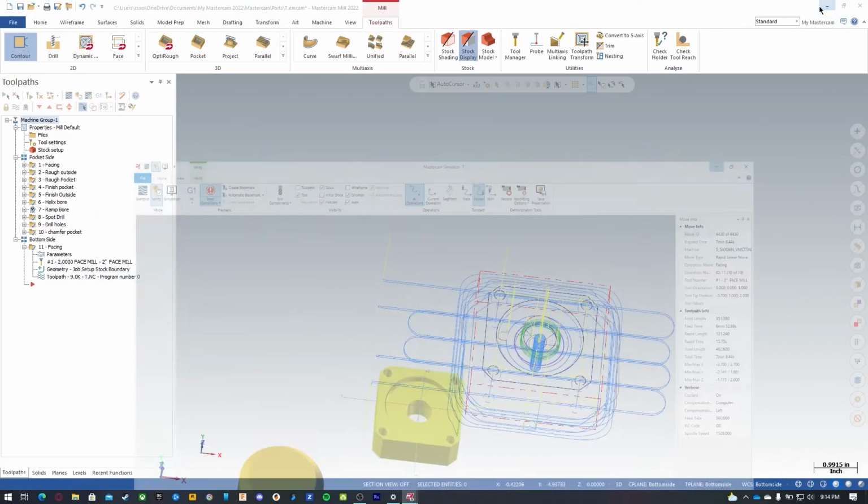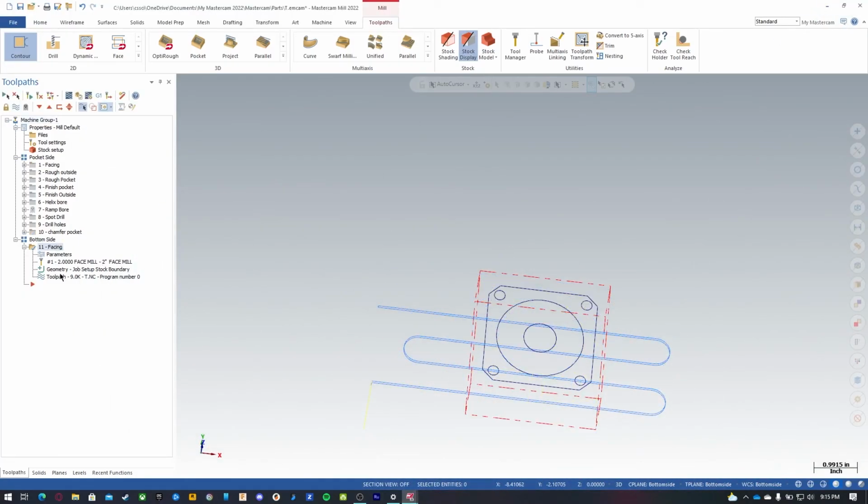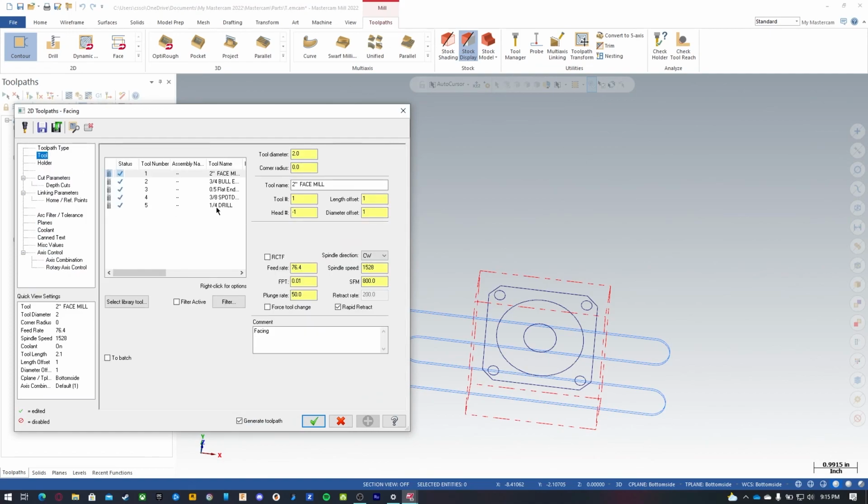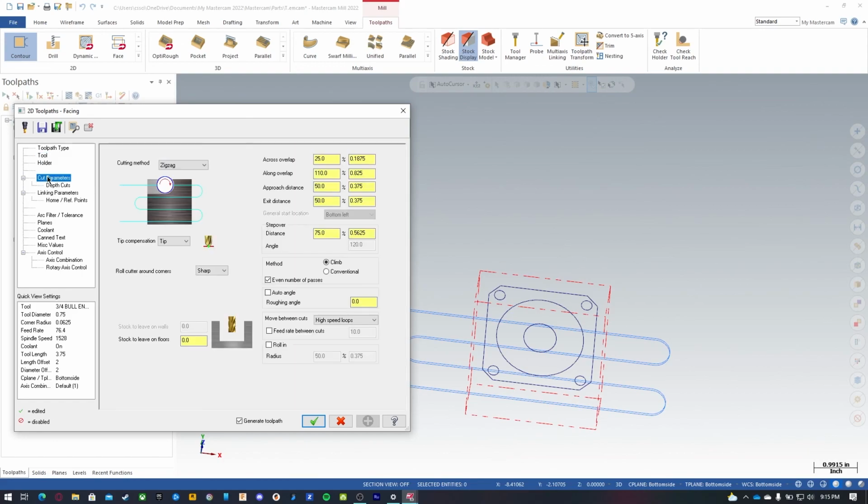So pretty simple, but there is another way. If you had more stock hanging off, you might be able to change to a 1/2 inch or a 3/4 inch end mill, and you can do dynamic, where it'll actually peel mill the stock off, and you can do high-speed machining. So we specify this at 10% of our step over, and we can increase our speed much more.